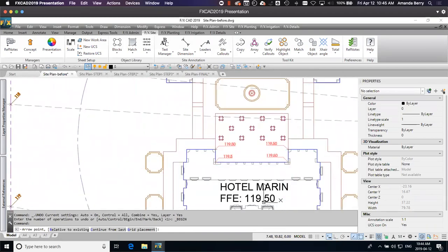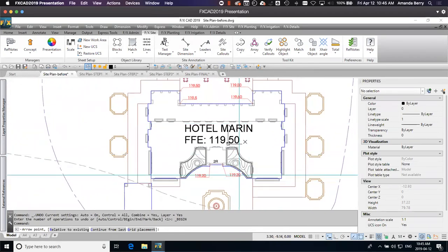But then what I want to do is, so this is actually pretty significantly lower than this side. And I have a walkway that's going all the way around here, and I need to drain positively all the way around the building. So there is probably going to be some foundation exposed over here. But generally what I'm going to want to do is start gradually grading down to over here.